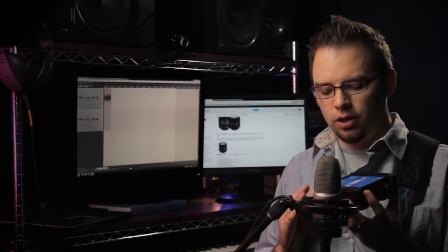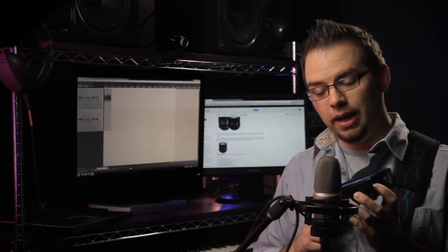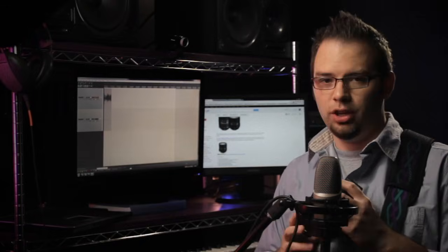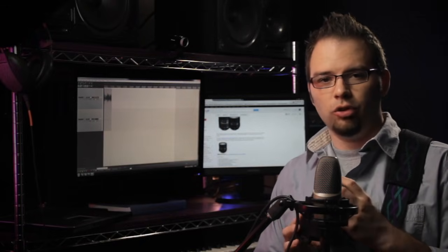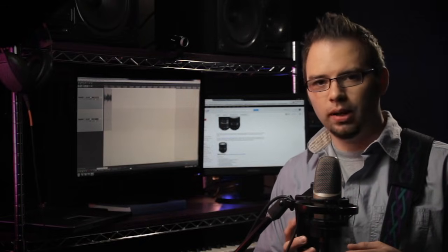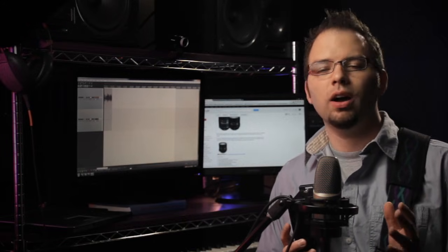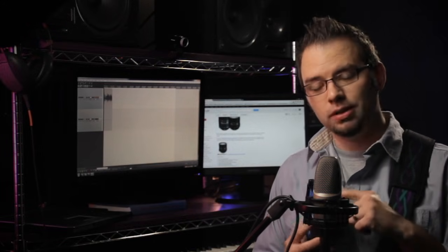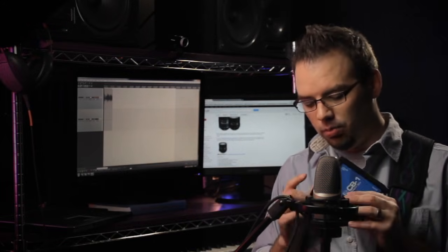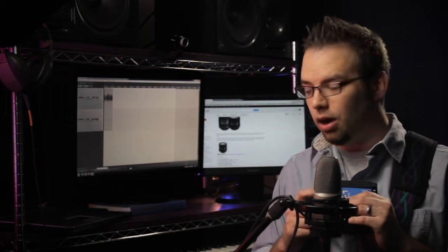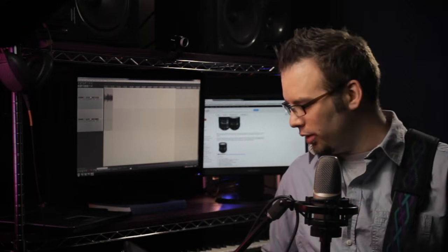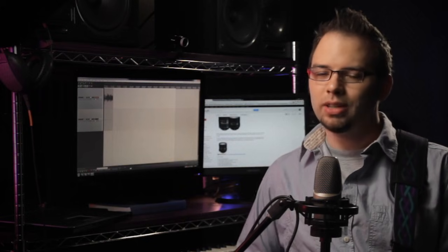Now, if you're recording more than 15 or 20 feet away, you may need to use a DI to get your instrument to an XLR and get that to your audio interface. You don't want to use a super long, like 50-foot long instrument cable. That's going to present all kinds of problems with noise. You plug your instrument cable into the input, you plug your output via XLR, and that goes directly into your audio interface. But because I'm so close, I can get away with this.